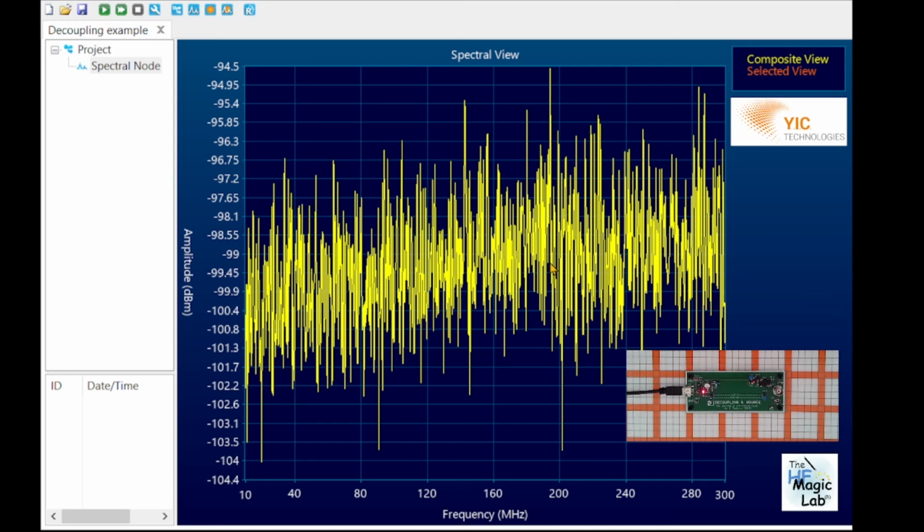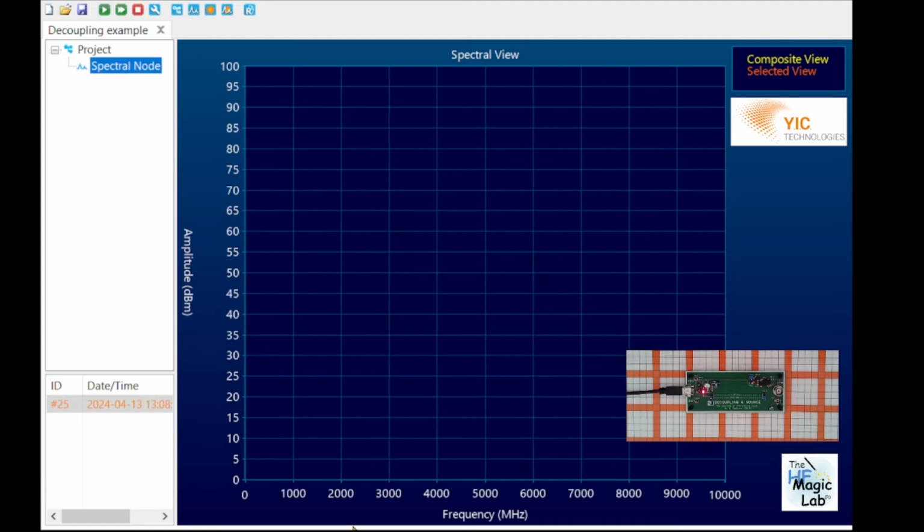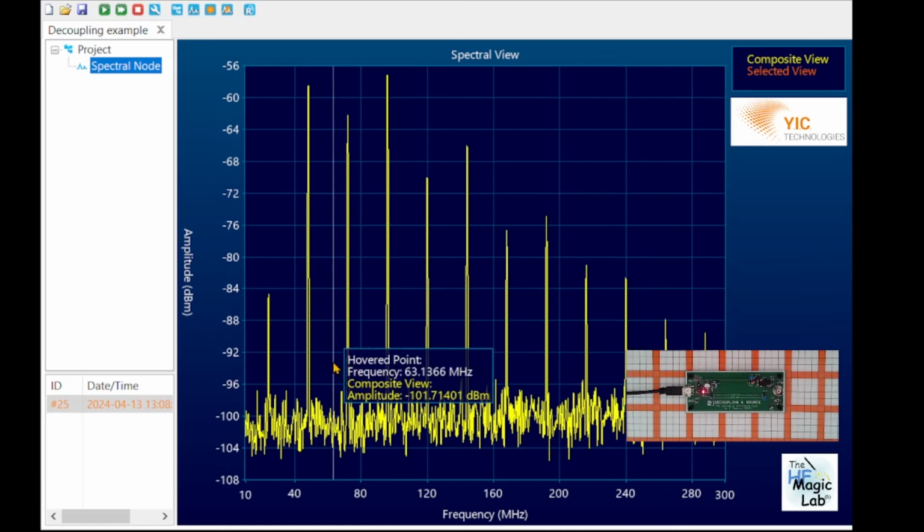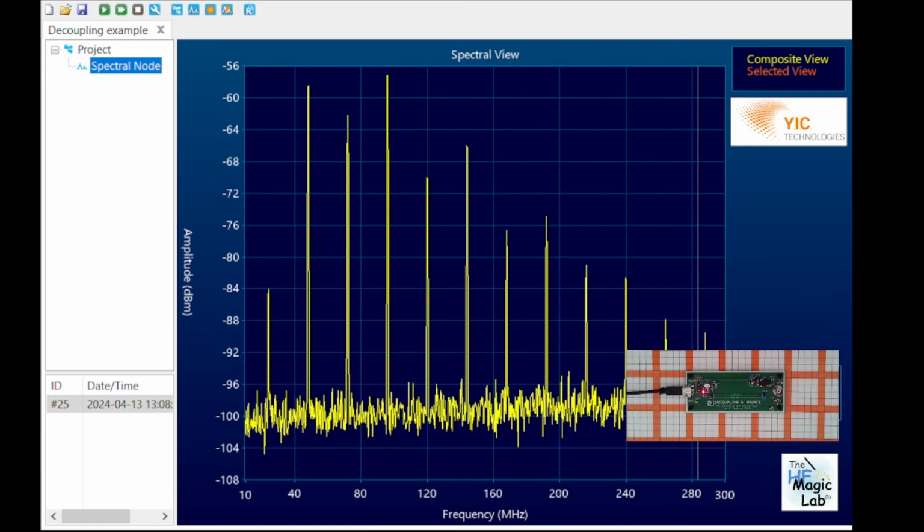Okay, but it's not necessary to activate all the cells below the PCB because the activity is well around the circuit. So we make OK and we run the spectral analysis. You can see how the scanner is identifying the activity of my digital system. The first harmonic, 24 megahertz, the second harmonic, 48, and all other harmonics with different amplitudes.